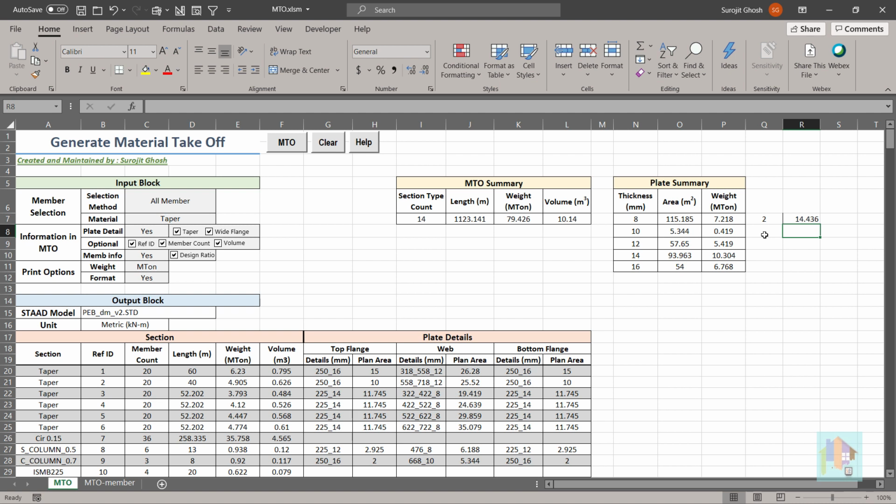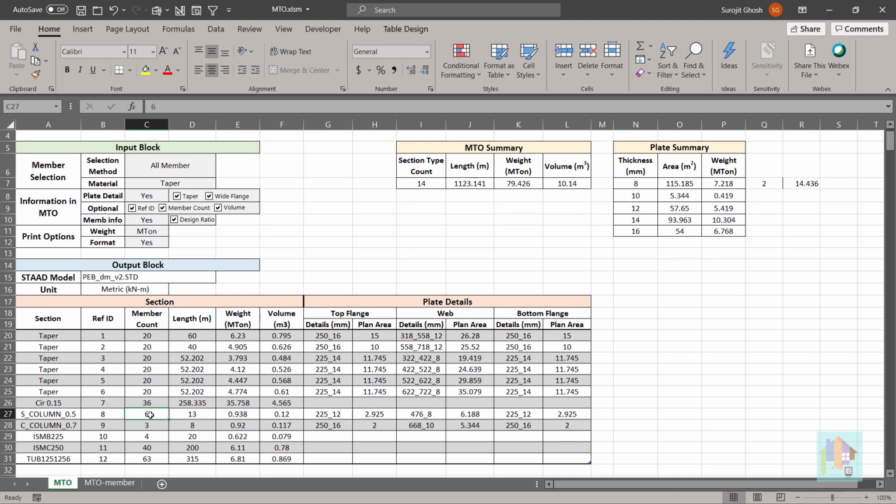If you are working on any steel project with built-up section, then I think this report will help you a lot. There is another page, MTO report for individual member. Before we explore this page, consider this scenario. This built-up I section is assigned to 6 members, and I want to know the plate length for each member. Length of each member might be different, and for procurement or fabrication purpose, we need to know the individual length of flange and web plate. How can we get this information?